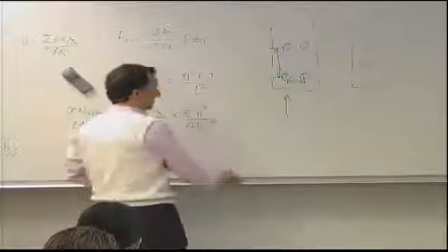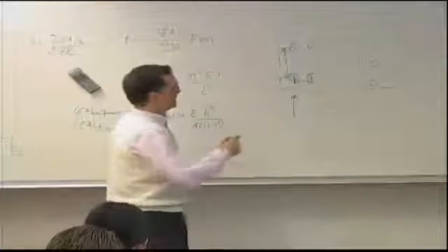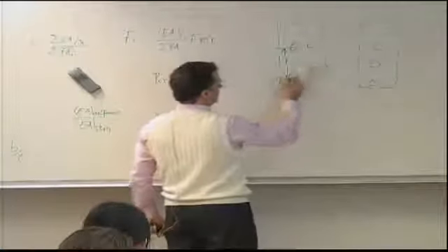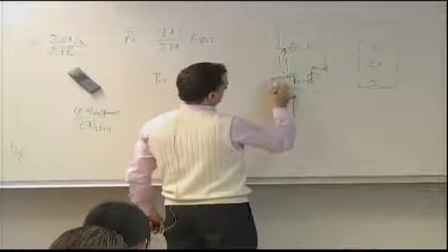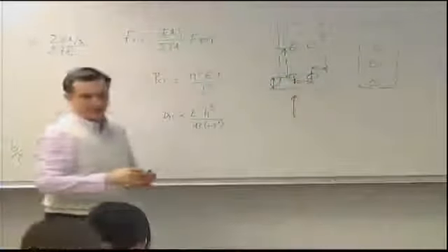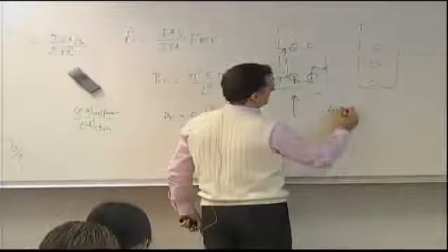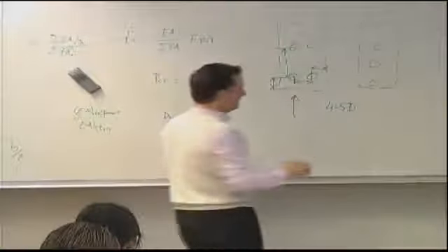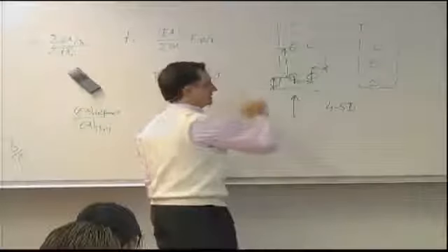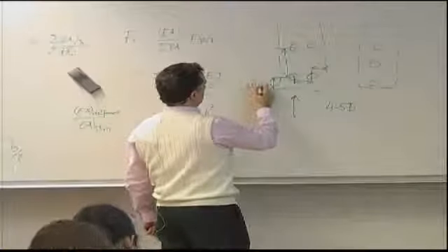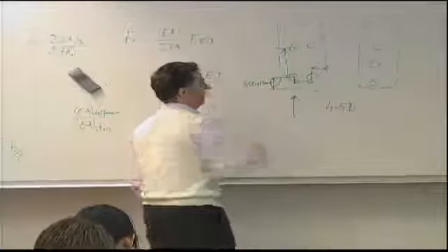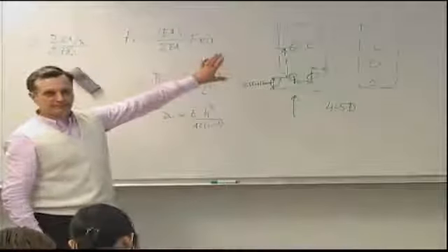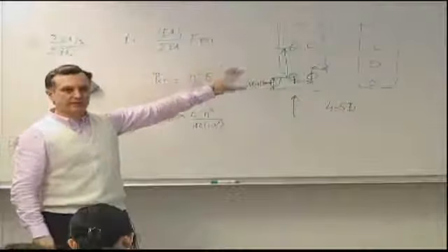There is one additional requirement that we will cover hopefully later on, which says, okay, what's the distance of each fastener from the edge? So there is the edge distance problem, and there is the fastener to fastener distance problem. Fastener to fastener is 4 to 5 diameters. For composites, for metals, you can get away with smaller, 2.5 even. Edge distance is 2.5 diameters plus 1.3 millimeters. Now, why it's 1.3 millimeters, we'll cover later on when we get back to this discussion. But these rules presumably cover those concerns.